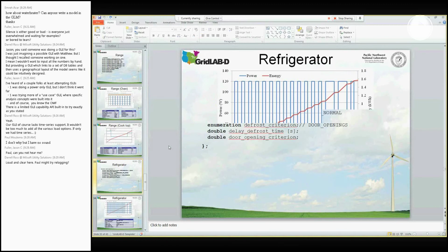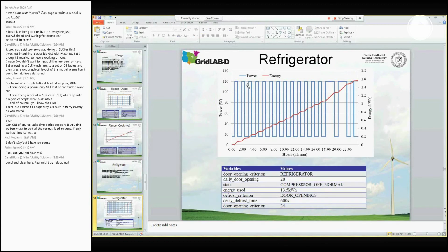And really that ends up looking like a pulse train of compressor cycles, and then you have these longer periods where it's doing what's called pre-cooling before the defrost cycle. So it actually cools the refrigerator to, say, 2 or 3 degrees cooler than normal, and then runs the defrost cycle and lets it heat up to 2 or 3 degrees higher than normal.